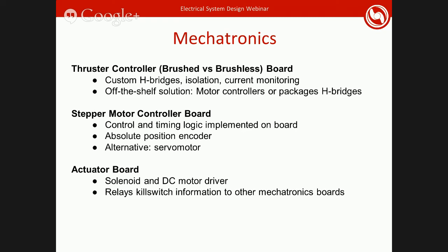As far as stepper motors go, very similar to our main thruster controller, we're implementing the stepper motor with custom H bridges, isolation, and the control and logic we implement on board using our own microcontrollers. And in order to address the earlier concern I mentioned about stepper motors only having relative positioning, we've added an absolute position encoder.